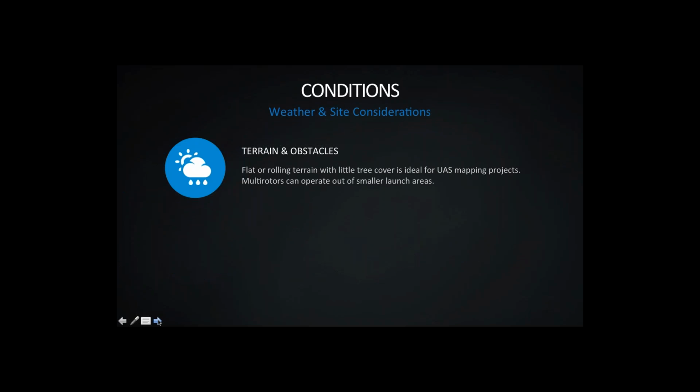In terms of terrain and obstacles, obviously having an awareness in terms of mission planning of, are there structures, are there bridges or power lines nearby? Is the terrain forested? Being able to see the ground in an open area obviously helps with photogrammetry and stitching images. Without using LiDAR or using photogrammetry, we really need to be able to see the ground to get decent elevation data, or X, Y, and Z for that matter. But we've worked in several areas at Airshark with severe terrain and had very few problems with cliffy areas as well, so it can be done.